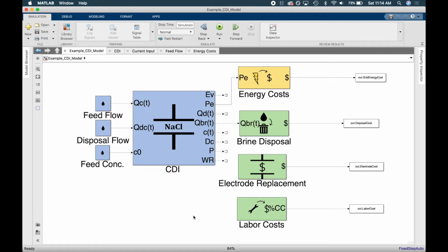What's happening is that all of the underlying physics and math side of it has already been baked into these blocks. And so when we specify these Simulink models, the Simulink model is what's being run by the UI that we saw previously. So this is where we do all of our fundamental modeling of the system. Luckily, all these come in pre-made blocks that we give to you, and so all you need to do is essentially drag and drop in Simulink and put in different periphery blocks as you're choosing.